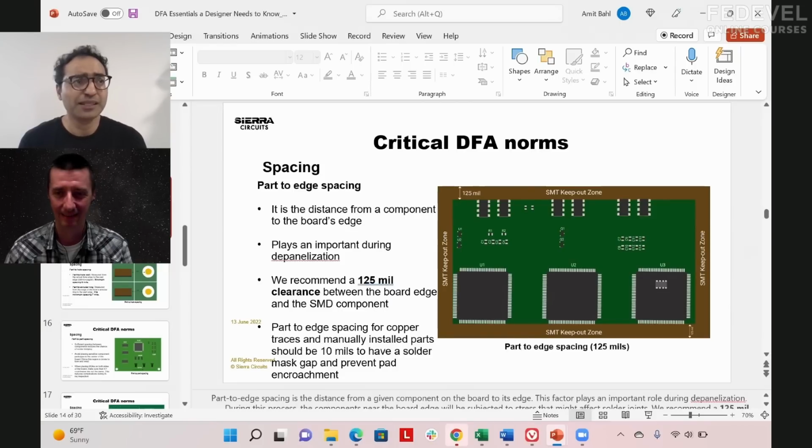So a solder paste machine that can somehow vary the thickness of the solder paste as it's putting it down, that doesn't exist. But modifying the tooling or the stencil will give different results. That's the deal. That's why the tooling step is important in general. The machine's not going to do it, but what can you do to set that machine up for success or what you want? So that's the tooling. I think this is an important part.